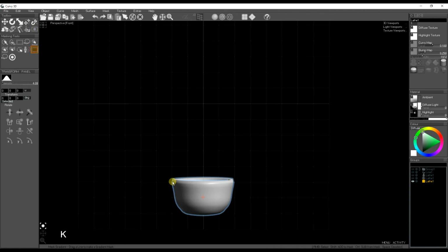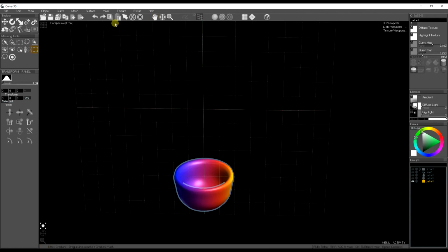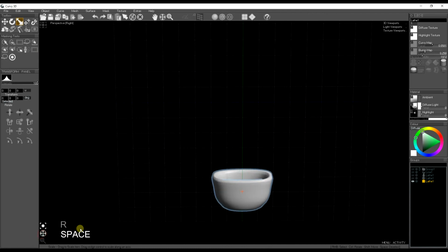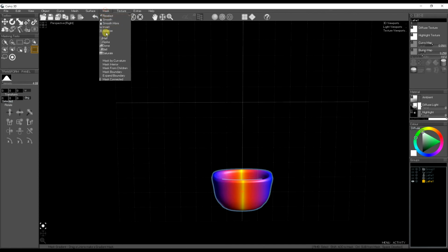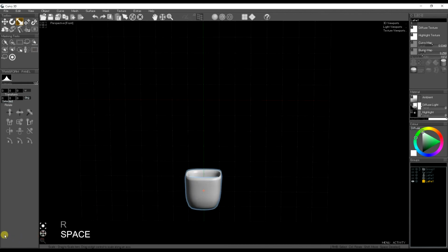Next, I want to add some flatness to the sides, so I'm using the gradient mask. That's a 4.1 tool. Solarize and invert lets me select the two opposite edges of the object. Again, from the other angle, using the gradient mask, dragging across the object, fill in a gradient mask. Solarizing and inverting lets me select opposite sides equally, and scaling those down squares the lathe.